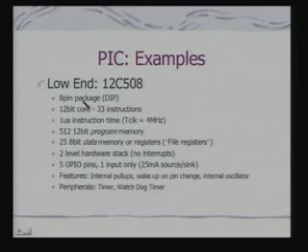It is typically an 8-pin package. It has 5 GPIO pins and interestingly only a 2-level hardware stack, no interrupts. And it has peripherals, simply a timer and a watchdog timer. The watchdog timer is there to recover, and the timer is for a simple application. So, for a very simple application, you can use this PIC.